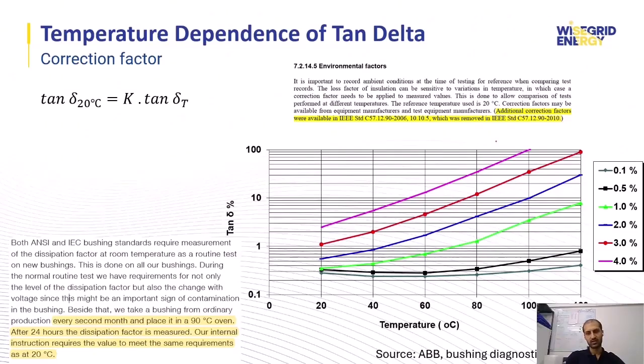If there is a significant difference between these two measurements, it indicates that the insulation is deteriorating and is no longer in its original condition. In such cases, the equipment should be monitored closely and potentially taken for maintenance or replacement.